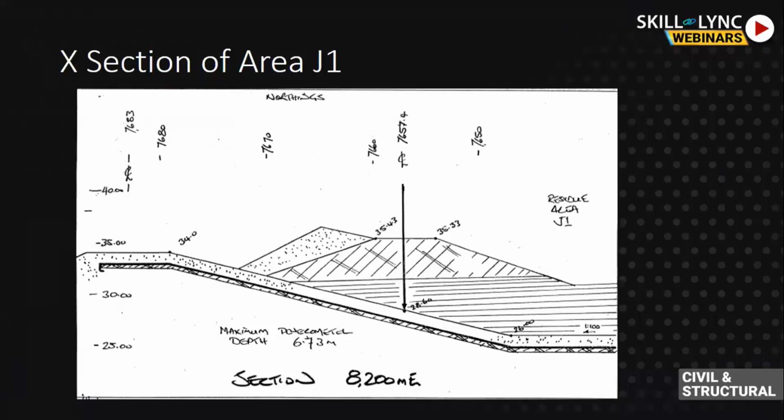Typical cone tip resistance, qc, values range from 2.5 to 6 MPa, with a mean of 5 MPa, which correlates with a shear strength of 125 to 300 kPa, a mean of around 250 kPa. The J1 trial embankment was constructed by ripping the red mud for drying prior to compaction, spreading the red mud in approximately 40 cm loose layers by a scraper, and then compacting with an 18-ton sheepsfoot roller.